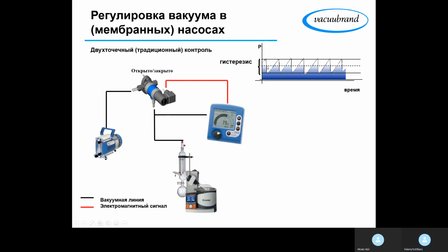We reach 75 millibars, and although we said 70 millibar, our substance starts to boil at 75, but we are going below in order to have the evaporation continue longer than 1 second, right?